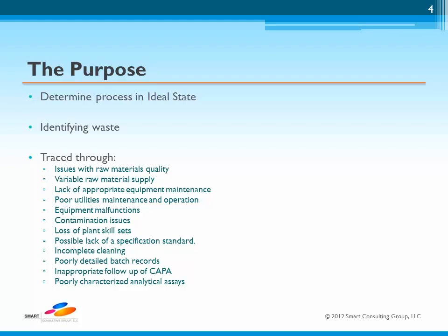So let's look at the basic format of a value stream map. In terms of its operational architecture, all value stream maps flow from left to right, with the raw materials for the next step being transformed as it moves to the right. The map charts all the steps and unit operations that are part of the process and adds a time component to that pictorial representation, which numerically exposes where the process resources are being expended.